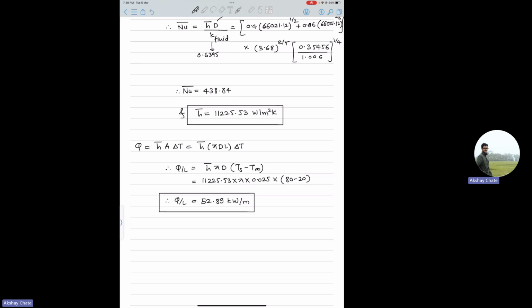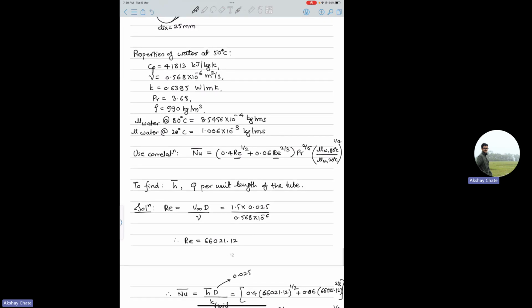Then there can be another set of questions where you have, let's say, one parallel flat plate with a flow over it, and then they'll say that the fluid viscosity is doubled. Then what is the heat transfer coefficient? So basically, you have to use the Nusselt number correlation, and there you just see that H bar is proportional to what power of that variable, and you just calculate. So those types of questions can also be there. I think we covered most of the things here. Internal flows will start from the next class onwards, because then it will be a wholesome discussion. Right now it will be piecewise, and then we'll see.